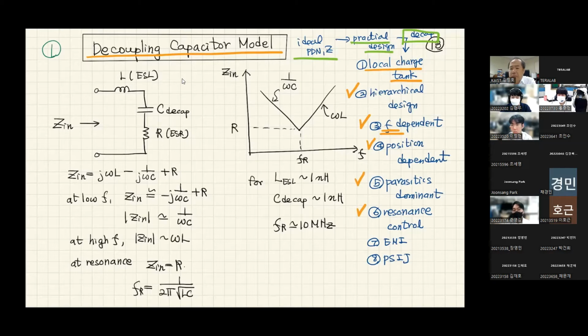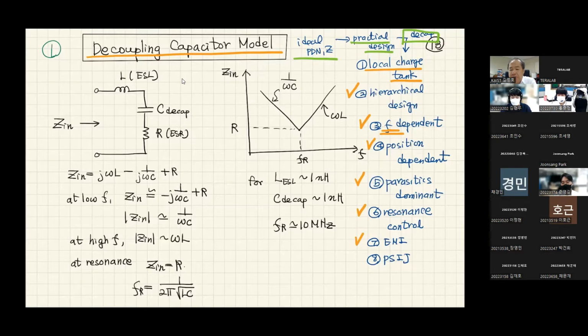Eventually, at the power supply node, if you do not have a proper design of the power distribution network, especially decoupling capacitors, you're going to suffer an EMI problem, because your power supply voltage is fluctuating and your power supply network is becoming an antenna and will radiate electromagnetic energy. Eventually it will interfere with sensitive systems, including RF receiver circuits, analog circuits, or sensor circuits. That should be avoided to secure reliable operation of your circuit and system.